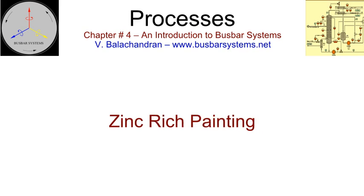Zinc-rich painting. Zinc-rich paint comprises 95% metallic zinc and is either sprayed or applied by brush on the surface of the steel to be protected. It is also referred to as cold galvanizing. Zinc-rich paint is applied when a galvanized component or structure gets damaged on the surface either during transit or during installation. It is also applied when a galvanized component or structure is subjected to mechanical operations such as shearing or drilling, exposing the base strata. The exposed surfaces need to be protected.